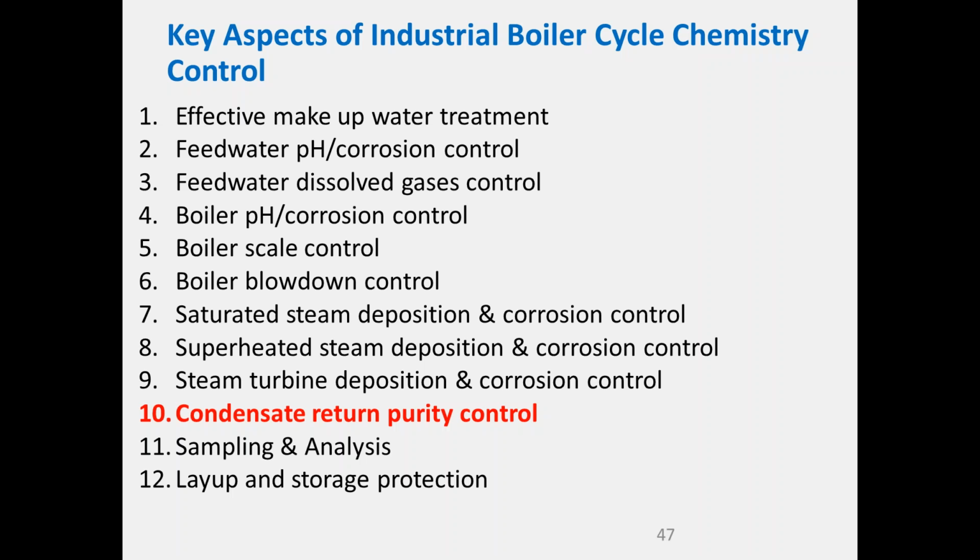No worries. All right, so the other big problem in industrial plants is condensate return purity control. This is a major one because say you're producing steam for an oil refinery, and you could get hydrocarbon return coming back. If you're a dairy factory site like Fonterra, you can get milk products coming back. If you're a salt processing plant, you may get brine. It could be anything.